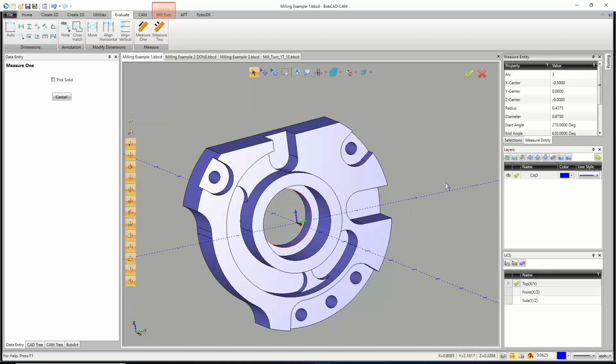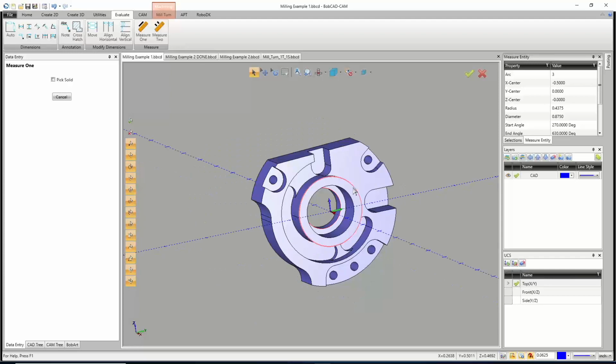So instead of using a 7/8 tool, we'll go with a 3/4 inch drill that's going to drill that out, and then we can feed into that drill hole to pick up and clean up that area. So that'll be a 3/4 inch drill, and then I could use the same center drill with that as well. So not too many tools on this one.